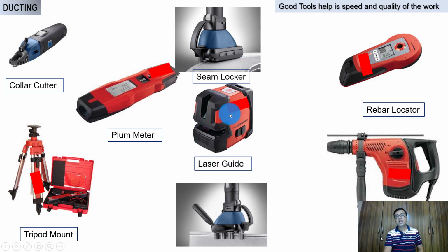You can get a laser guide which can again give you proper marking. You don't have to go and physically mark. This will properly set you, giving around 20 meters this side, 20 meters that side. Proper marking. You can easily go and do the drilling and fastener.